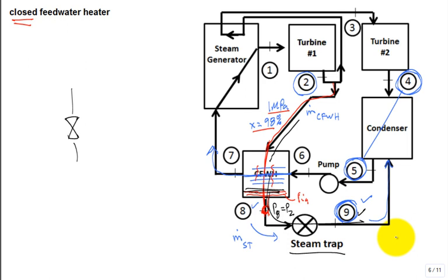You can see different schematics and designs of them. It'll fill up with liquid, the float will go up, and it says, oh, you're too full. It kicks the valve and flushes that liquid. But then the float falls and it shuts the valve. Make sense? And you can buy them, and they're designed.